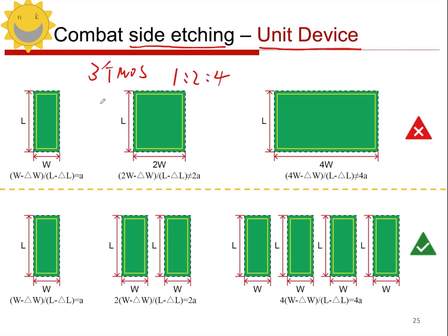then we should draw its gate area, right. For example, the blue area is our gate area, so we first draw the first transistor. We draw a MOSFET like this with a W over L, right? This is W to L. When we draw the second MOSFET gate, because its width ratio is twice that of the first one, we change its W to twice W, right? So when we draw it, it is twice the W to L. And for the third one, of course, it is 4 times the W to L, right? So we draw 3 transistors, and their width ratios are W/L, 2 times W/L and 4 times W/L.